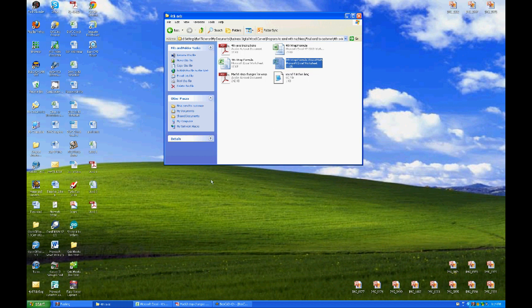But let me show you what you have to do on the Mach 3 setup. If you'll click on this, once again, this is in your fourth axis folder: Mach 3 step change for wrap. This is what's going to tell Mach 3 the diameter of the cylinder.